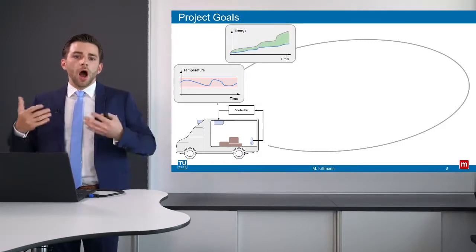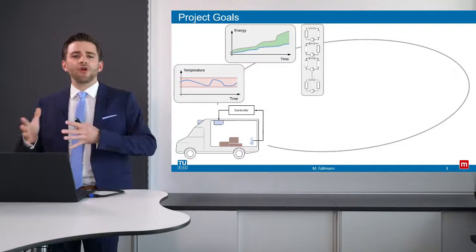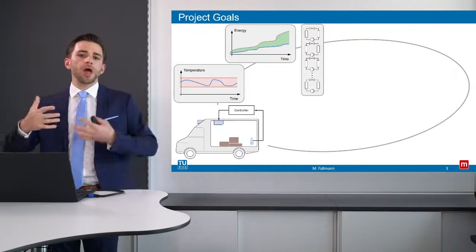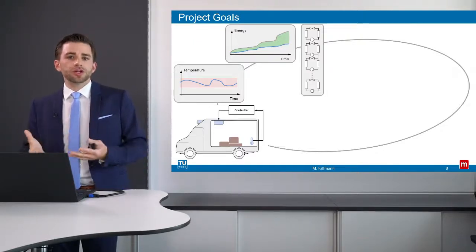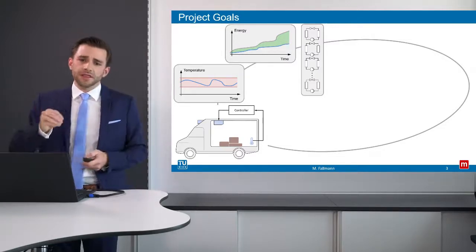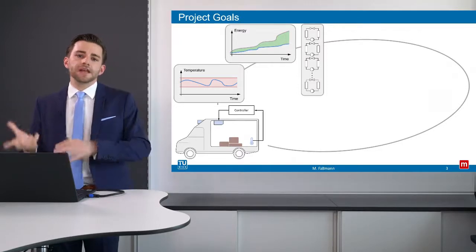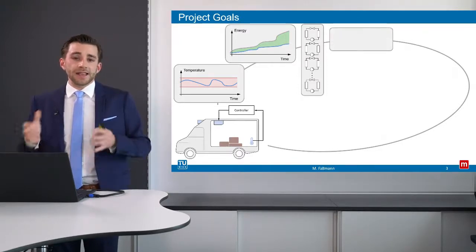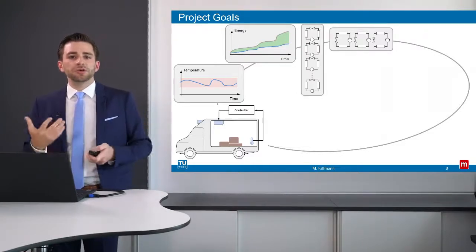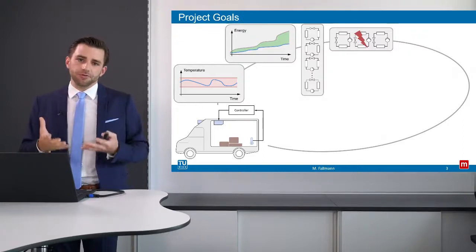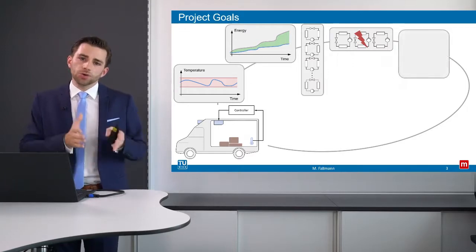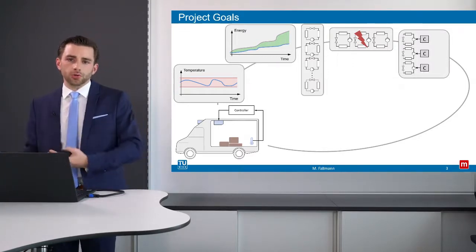Furthermore, our control scheme should be able to handle a varying number of cooling units. For example, a truck that operates in the north of Europe may be equipped with 2 cooling units, while a truck that is used in a region close to the equator may need 4. And fulfilling this aspect is also vital for the fail-safe performance of the overall system. In this sense, we are asking for an algorithm that still performs adequately, albeit one or more cooling units exhibit a fault. And to further improve reliability, each cooling unit should be equipped with its own controller.